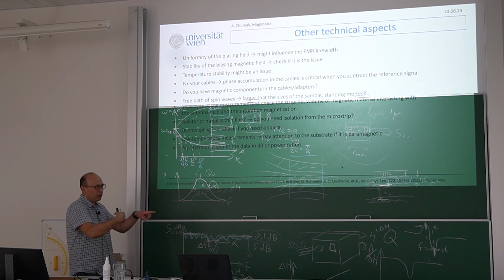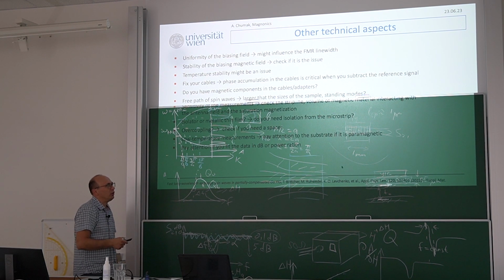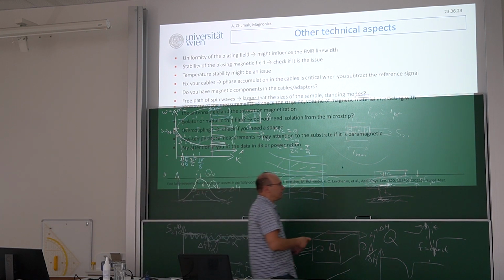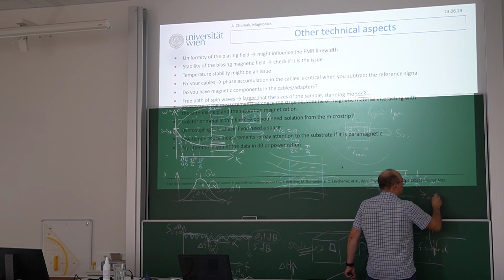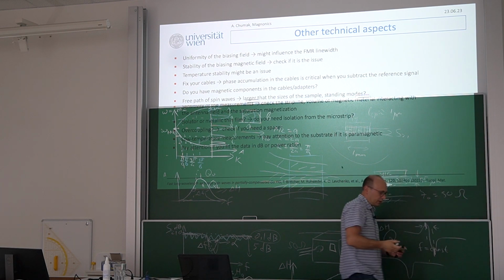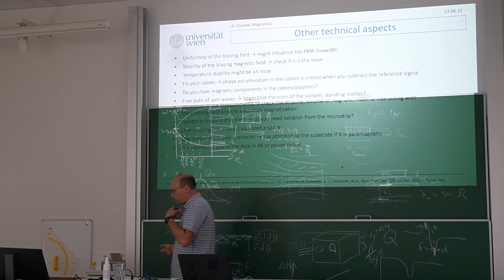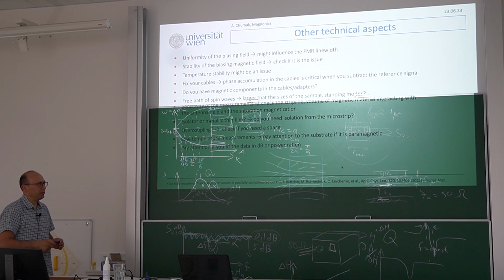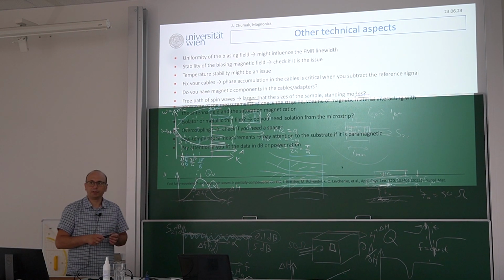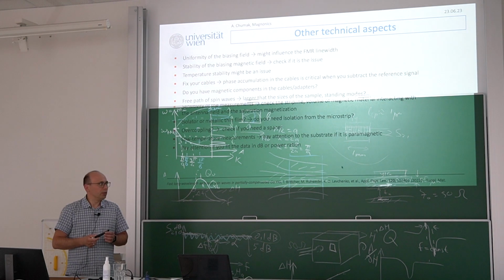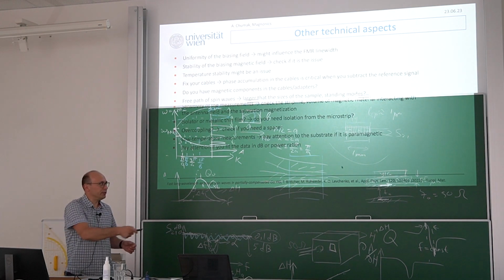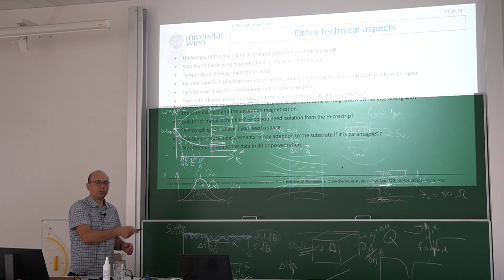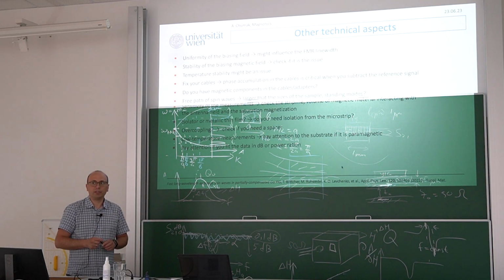Not only that you always have two currents running in opposite directions, but also that you have a characteristic impedance of 50 ohm, so that everything works well. Otherwise you will have strong reflection, and you won't be able to perform proper measurements, because the majority of the microwave signal will simply be reflected. But for CPW, I would not need it. You can have both. There is CPW with ground, and there is CPW without ground. Not necessarily, you can do without ground.